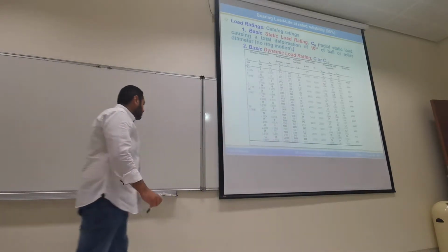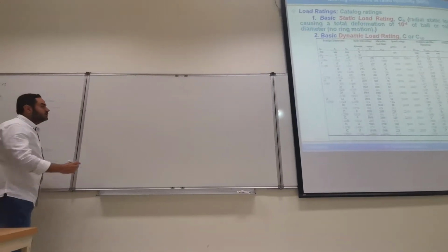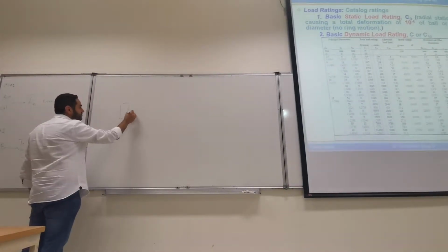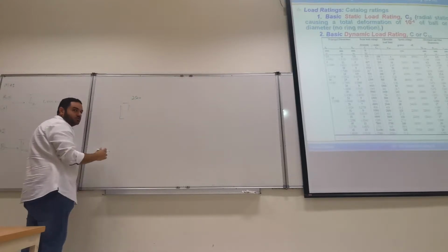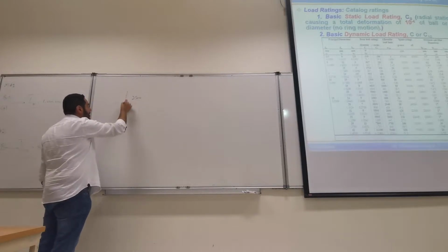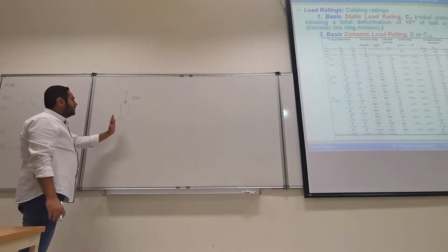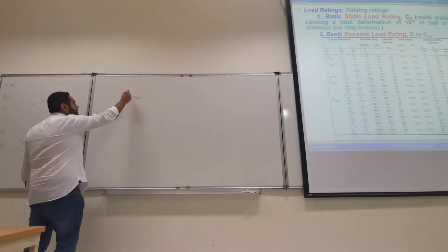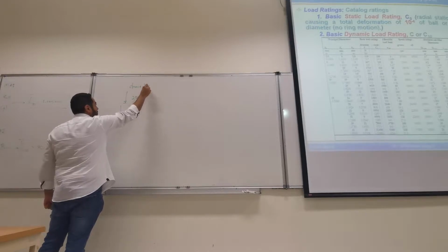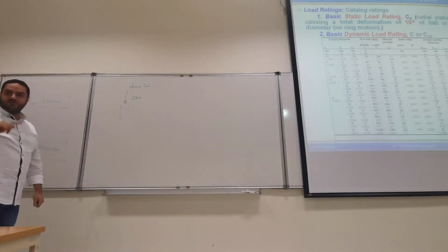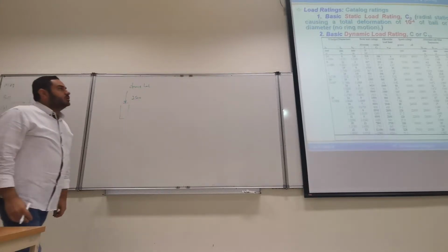What is the dynamic load? Now I said that we run to 1 million cycles. So they will have about 2,500 bearings. They run together at the same time, and they are under the same load. So the load applied during the test is the dynamic load. Why is it called dynamic? Because the bearing is in operation. It's rotating.